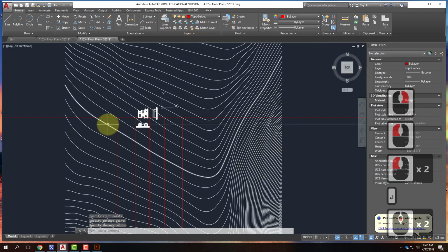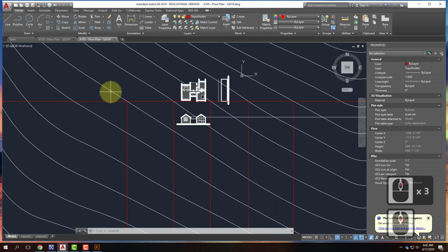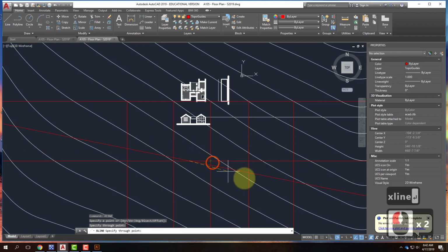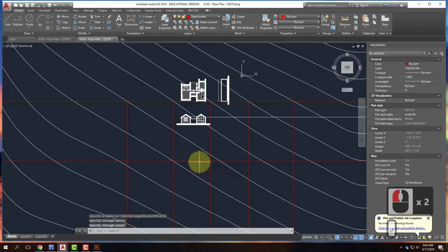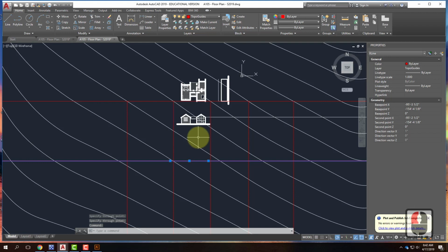So I haven't done all of them. I've just used a set of them that are kind of nearby. Now on each one of these topography lines, I'm changing vertically by a foot. So I know that there's going to be a series of lines that are changing by a foot each. Let me go back to my construction line. So I'll go ahead and type X line. And I'll pick a point down here in space just as a starting place. So there I am. I'm going to take this and copy it up at 1 foot intervals.